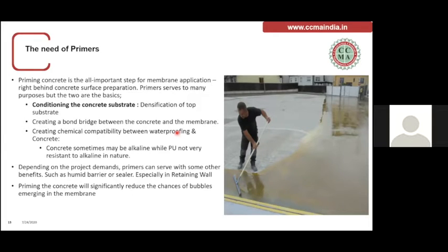Now, talking about the primers. Now, the concrete where your waterproofing has to come. The top layer of the concrete, the primer acts as a densification, which I have already discussed. The top layer becomes densified using a primer. It also acts as a bond bridge between the concrete and the membrane. The primer penetrates inside the concrete, and waterproofing membranes have a very good bond with the primer. The system works very well together.